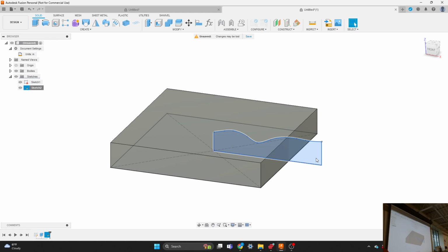Did I do this wrong? Well, I was thinking instead of doing your revolve again, we would just do this right here. Oh, and I drew mine down. You drew yours up, mine's upside down. It doesn't really matter. But I was thinking instead of cut, we would do intersect. Then we would have just the intersection, and it would be right side up. Cool.